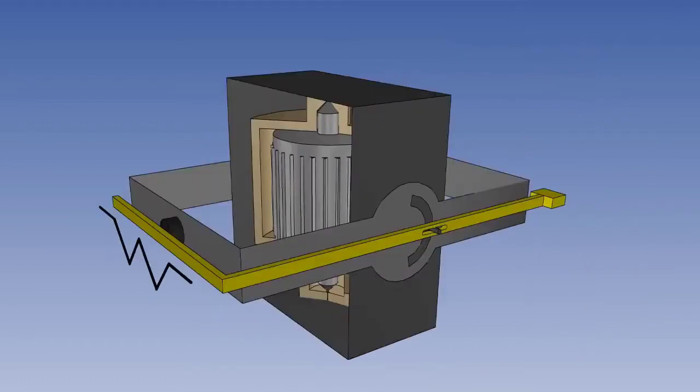The earth gyro in the artificial horizon or attitude indicator may be air-driven or electrically driven. Let's look at the air-driven version first, and the errors associated with it.